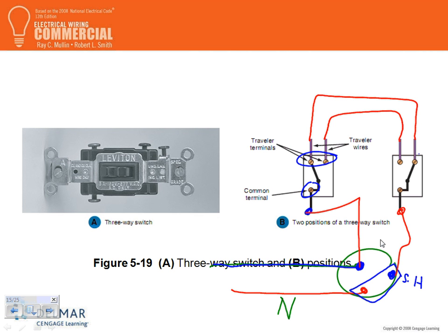So the most important thing with 3-way switches, guys, is that the travelers are tied together. The common can go either to the switch, either to the hot, bringing the circuit to the circuit, or to the lighting fixture. That's basically what I'm trying to illustrate here. Questions? No?